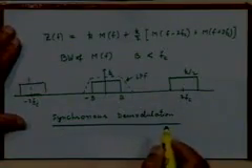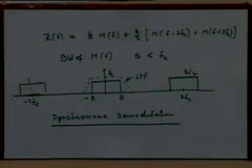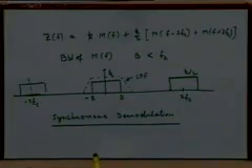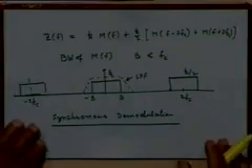So this kind of demodulation is called synchronous demodulation, whereby we imply that the demodulating signal or the local carrier at the receiver should be in perfect phase and frequency synchronism with the carrier of the received signal, right? Because if it is not so, we will not get a perfect demodulation. Let's see why, right? So let's look at the effect of loss of synchronization. If your synchronization is not perfect, what will happen?